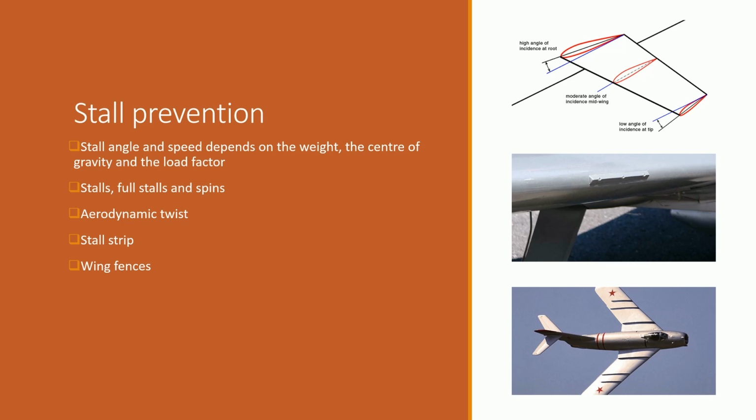Another method is a stall strip, which can be attached to the leading edges of both wings on an aircraft. These strips are triangular in cross-section and encourage the wing to stall at a certain spot on the wing. It works by creating a sharp angle of attack between the relative wind and the angle of the triangle. This is relatively higher than the angle between a curved leading edge and the straight edge of the triangle. This causes the boundary layer to become turbulent sooner. Like the twisted wing, the root stalls first, then the wingtip.